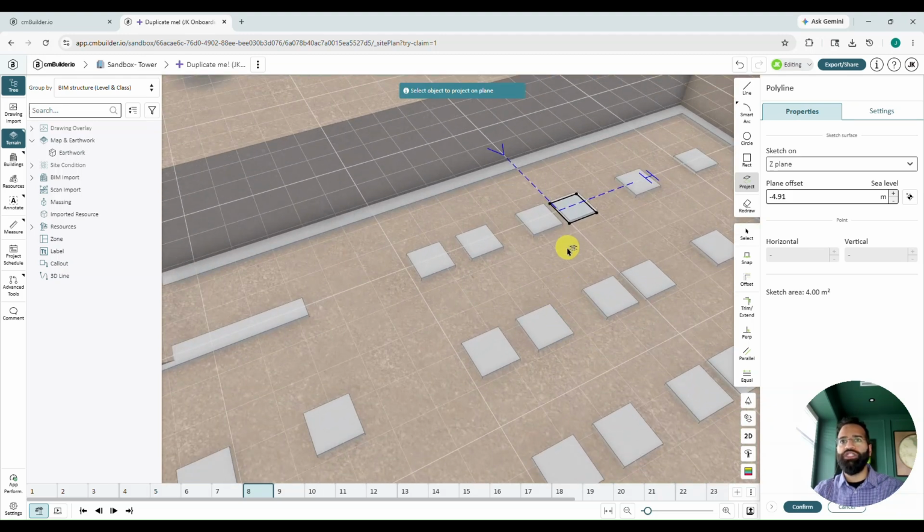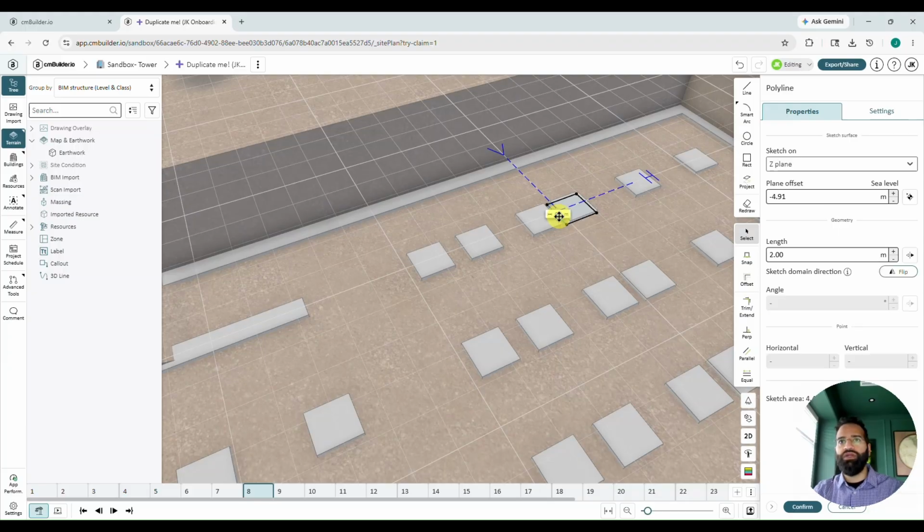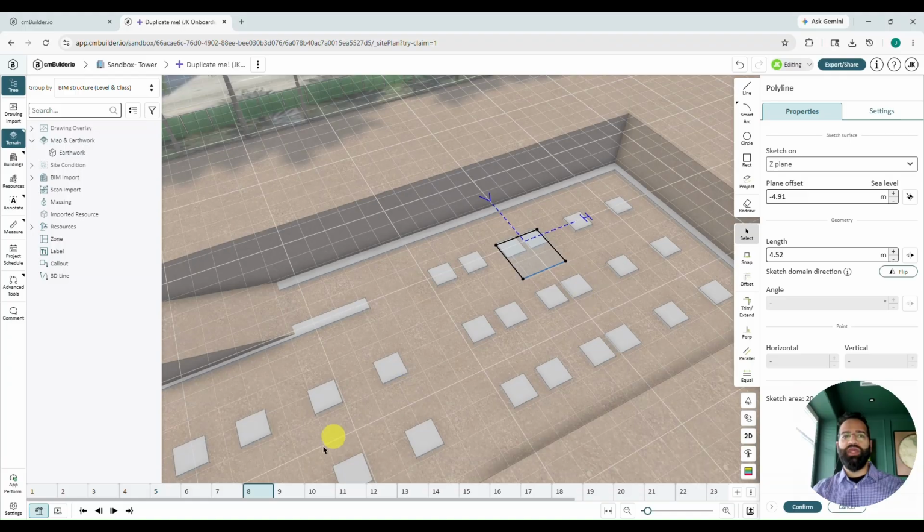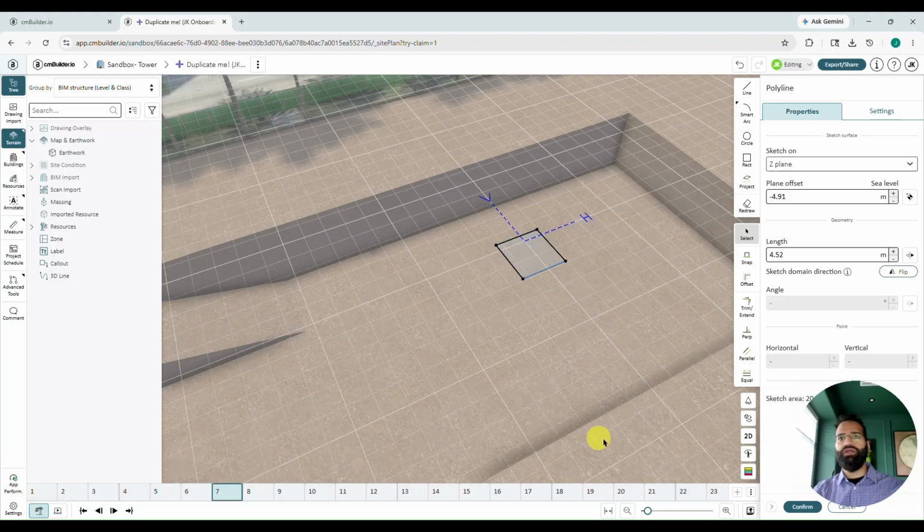Today, I will just generalize a little bit here. I'm going to hit escape to turn off the project function. Click and hold on a line and use the shift key to adjust the positioning of these lines while remaining parallel to the original orientation. And then we'll head back to milestone 7, and that will just represent one detailed excavation.